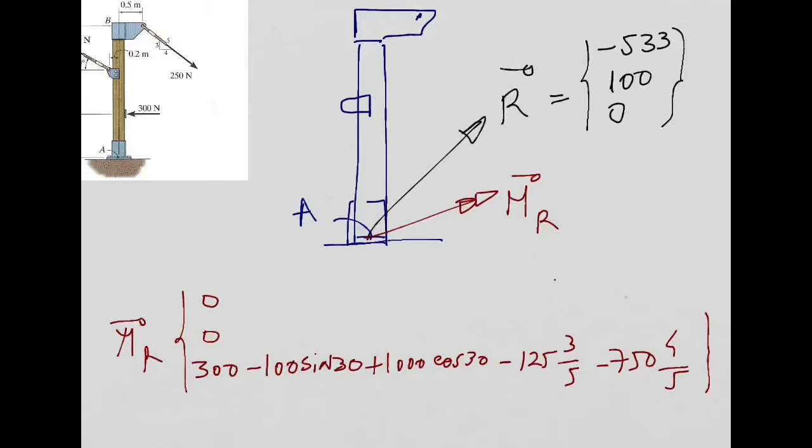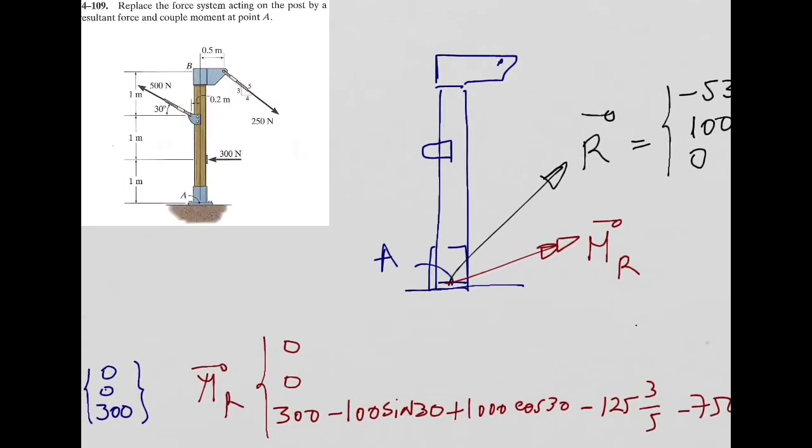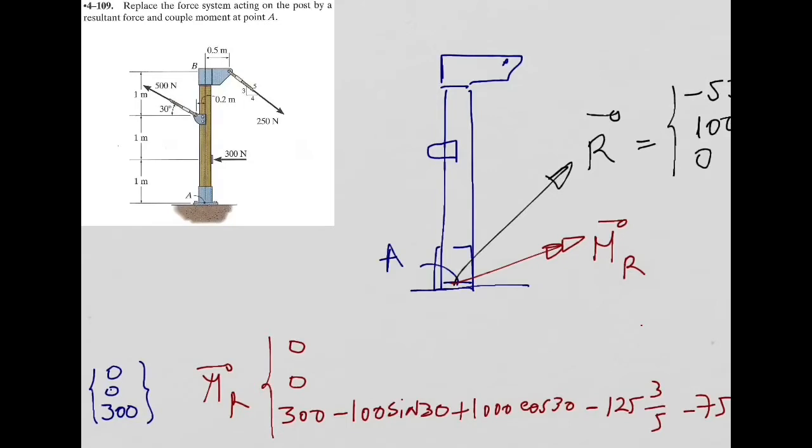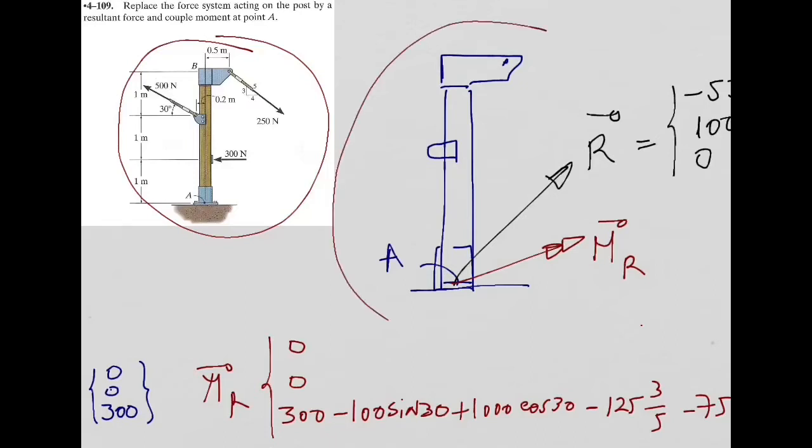So you can compare the two systems. The first one, where you have three forces applied at three different points, and you can compare with this one where the resultant of the forces and the resultant of the moments are applied at one particular point, point A. Right? This is very critical. In the afternoon, we are going to do a more elaborate example using this, okay?